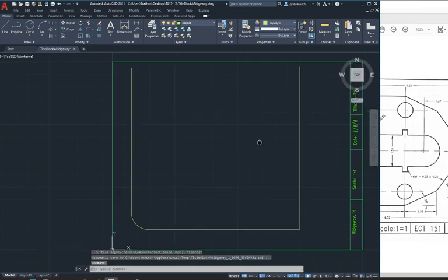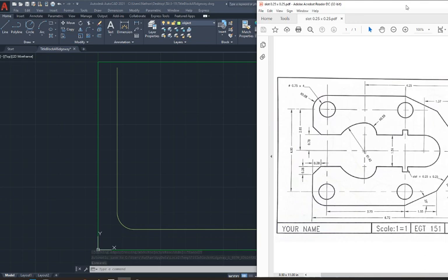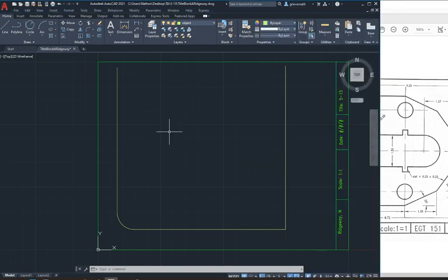The next thing I'm going to use is, let's see, there's a couple ways we can do this. I believe the next thing we should do is draw these circles here. This is because, due to these center lines, we know that these circles share a center with the circle we just drew. So if I use the center tool, dimension center, if I type DIMC, press enter, I can mouse over this and click. And now I've marked the center of that circle we drew earlier.